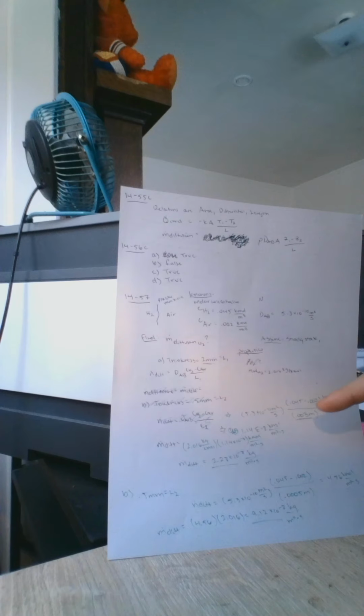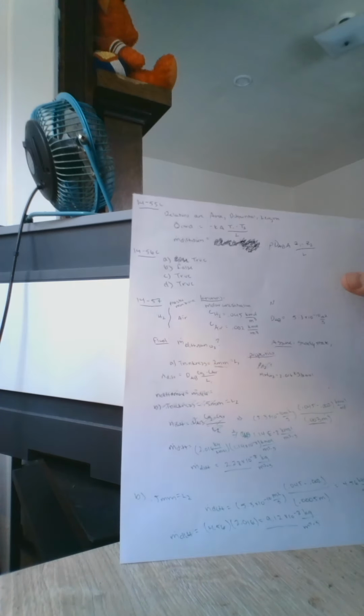We used N diff equaling the diffusion coefficient times the concentration of hydrogen and the concentration of water over the thickness of the membrane to calculate the N diff, which then can be converted to a mass diffusion rate by multiplying by the molecular weight. This was then repeated for the other thickness down here at the bottom, the 4.55 millimeter membrane.